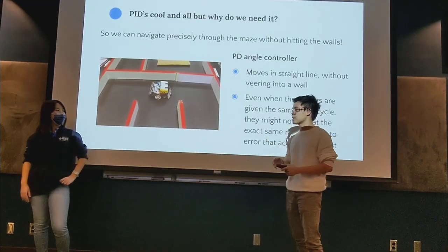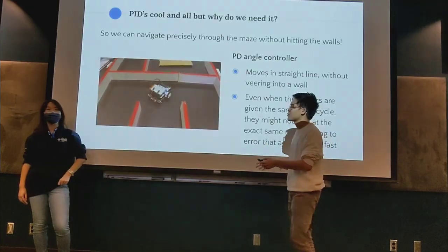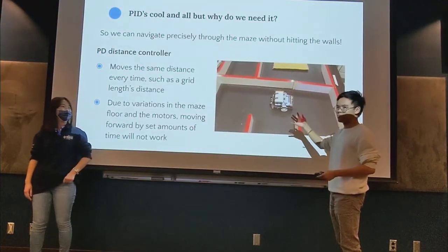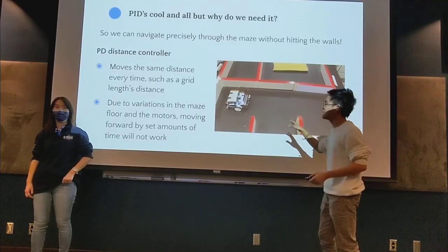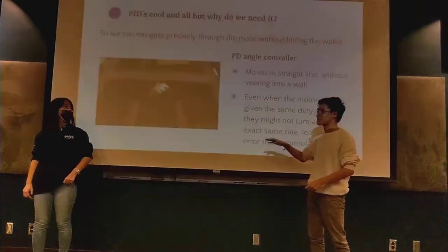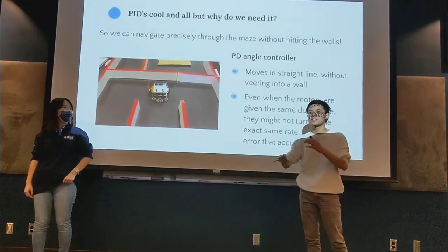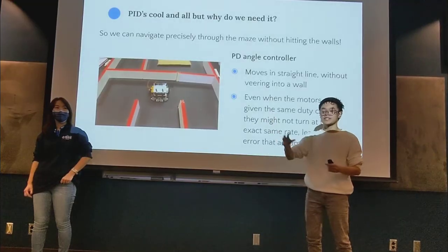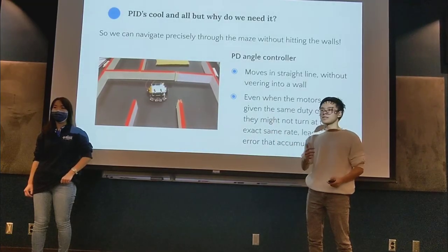So the way we're doing it right now, we're going at a really slow speed, so there would be little to no skid. But if you want to run it at higher speeds, what you would do is add an acceleration constant, so you're not changing speeds too rapidly, because skid only happens when you're accelerating or decelerating really fast. Does that answer your question?